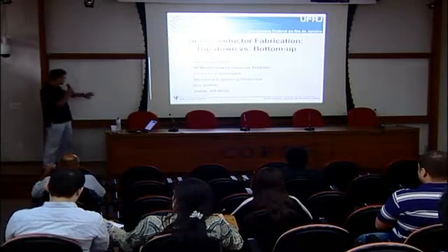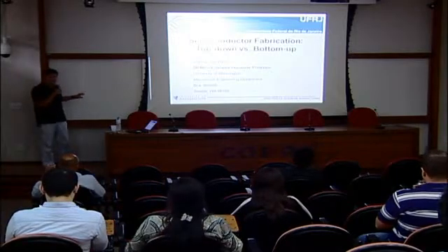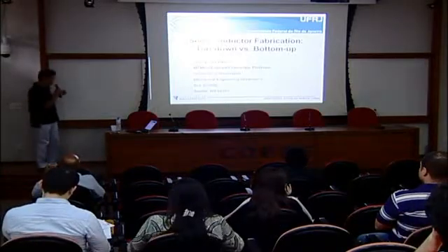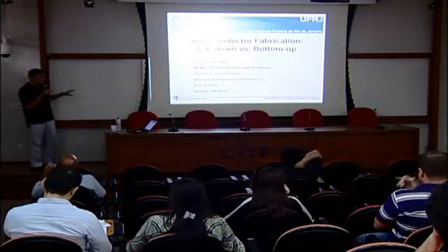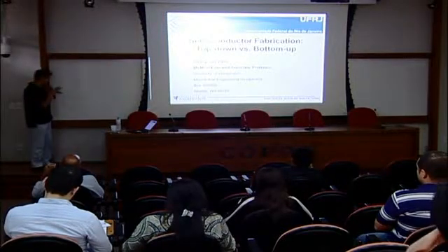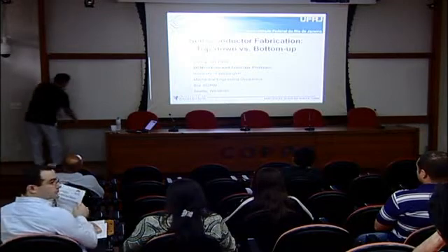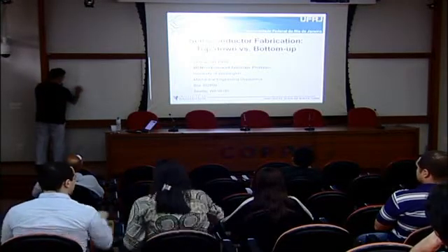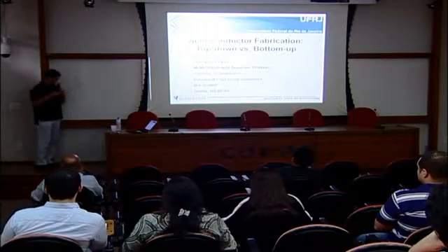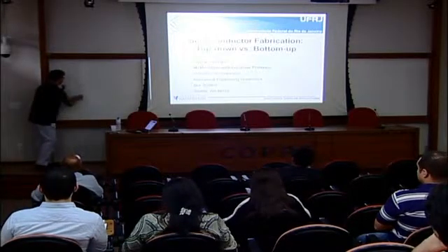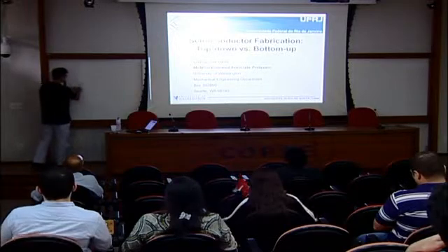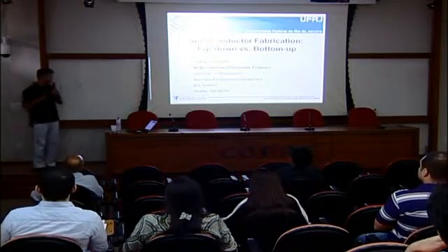So the bottom-up approach is at a very early stage, and the top-down is a fully established method. However, under 10 nanometer, we do not have a tool to make it smaller. That's the problem. Also, when we think of a 10 nanometer silicon structure, for instance with a 10 nanometer diameter, the surface of silicon is quickly oxidized in air. So the material is not silicon anymore, it's silicon oxide. What that means is when we make it very small, we cannot realize the performance of silicon anymore.